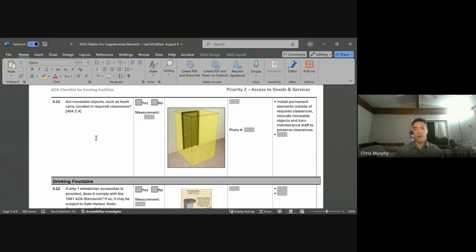So whatever orientation your door specifies the maneuvering clearance is, let's say there's a short protrusion in the bathroom, it could be a grab bar that goes up to the door frame. That's technically not allowed, except that the maneuvering clearance can be offset by up to 8 inches. As long as when doing that the maneuvering clearance doesn't overlap anything else that's permanent, you'll be good in that situation.